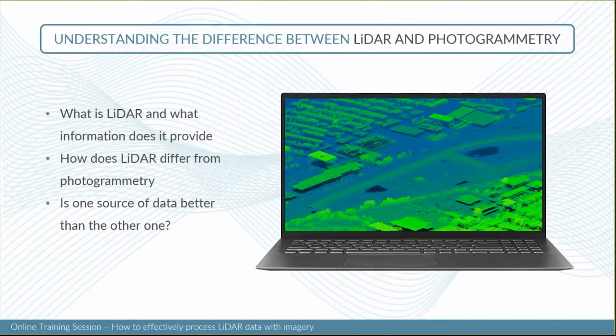Another disadvantage is that sometimes, if you want to bring the intensity into your analysis, there's a phenomenon of striping for the intensity, because the intensity really varies with the range and also the elements that the pulse is hitting. So when you look at your intensity images, you could find some striping from flight line to flight line. However, it seems that some techniques are trying to solve this problem in order to normalize the intensity over different flight lines.